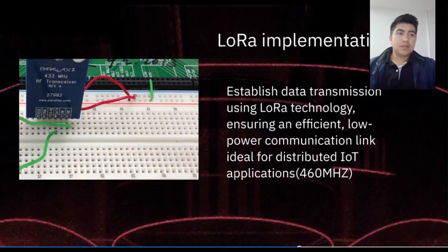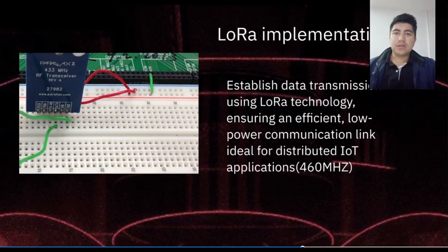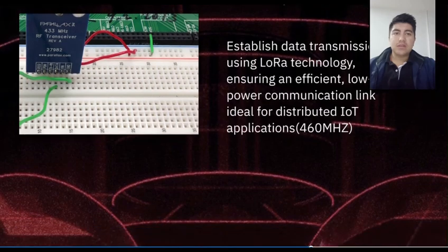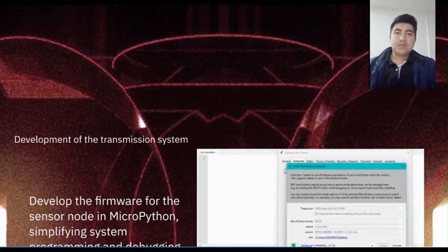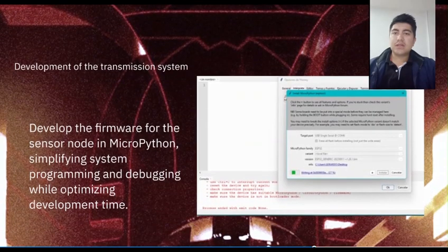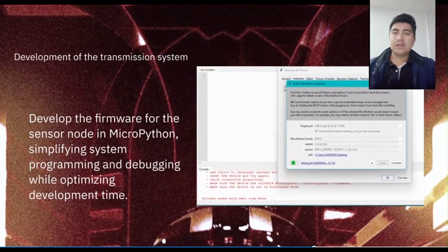Methodology, installation and configuration. Python, Thonny, and MicroPython were installed on the ESP32. The firmware was flashed, the COM port was configured, and available boards were verified. In the end, the ESP32 was left ready to run the script.